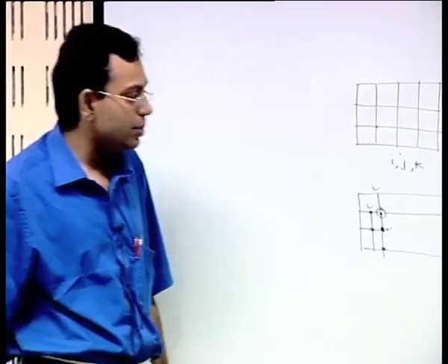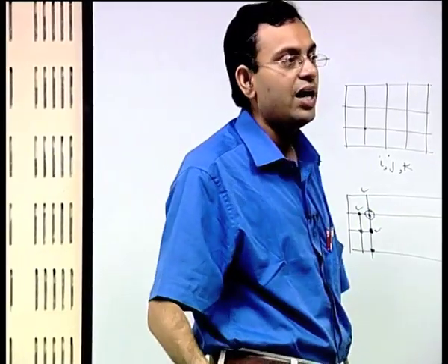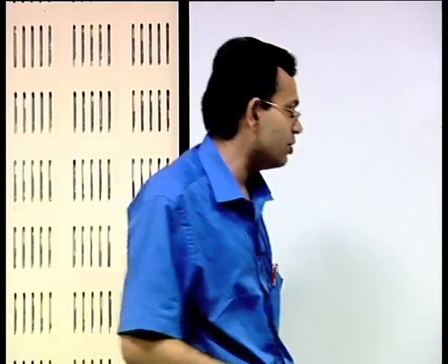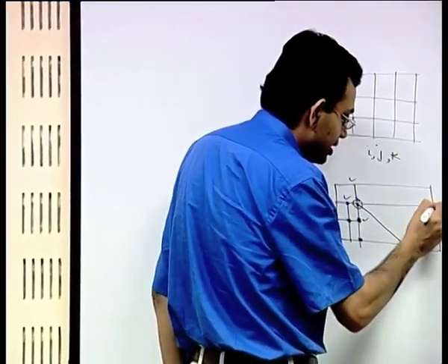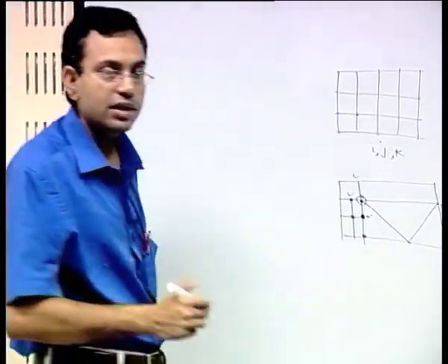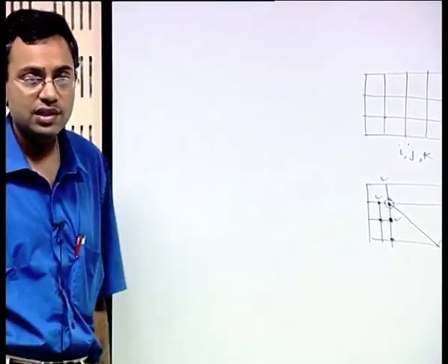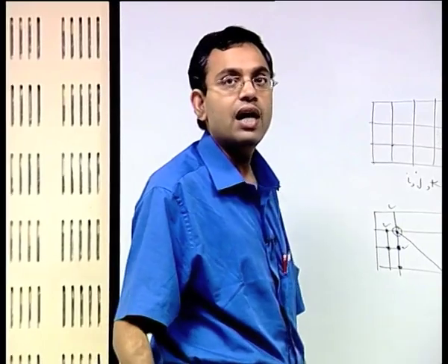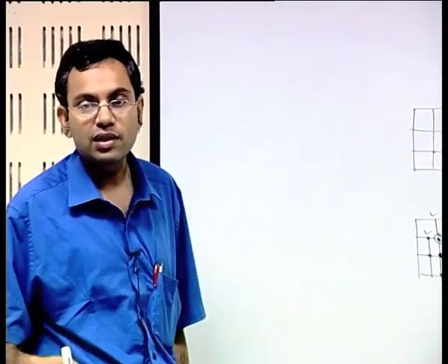So it is possible to have an unstructured mesh with rectangular grids. You can of course also have combinations of triangular, rectangular and all sorts of shapes. So it is very much possible to have an unstructured mesh with some control volumes that are rectangular.